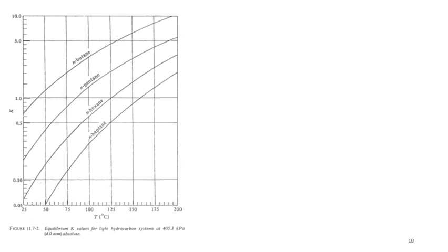So we just have to try the first temperature. So let's take T1 as 65 degrees Celsius as our first trial. So what you do is you just prepare a table so that you can just fill in the values when you have read the K values. So you have components A, B, C, and D. So you have Xi at the feed. Okay, so it's 0.4 for A, 0.25 for B, 0.2 for C, and 0.15 for component D.